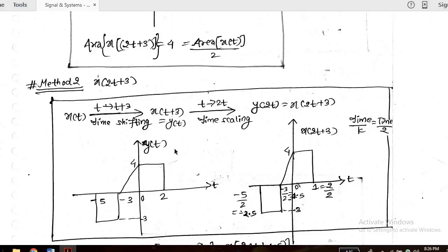So you shift x of t by 3 units to the left, draw it, and rename it as another signal, y of t. Now you are reading it like this: t plus 3 is completed. Now see, proceeding from right to left, first you encountered 3, it is a t naught factor, the shift variable value. Keep it aside, that is the shifting you have just done.